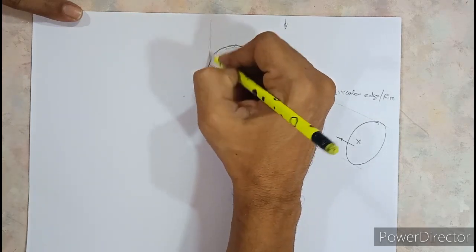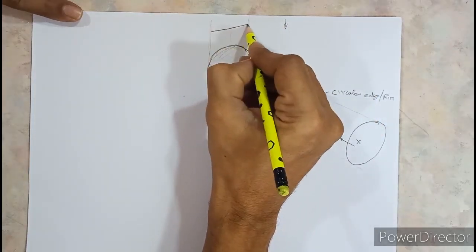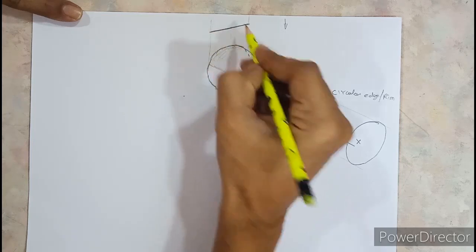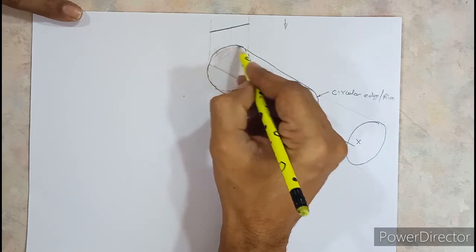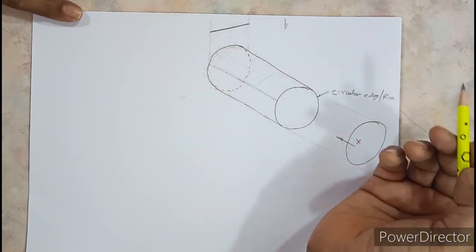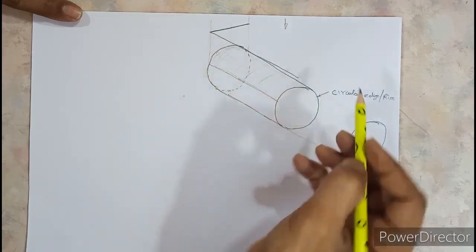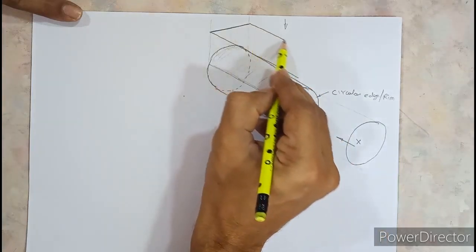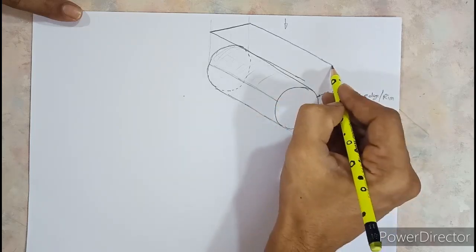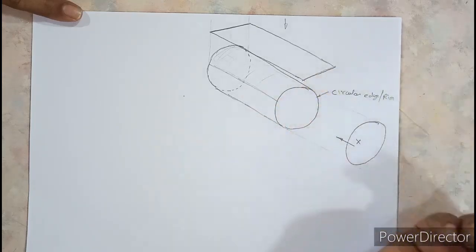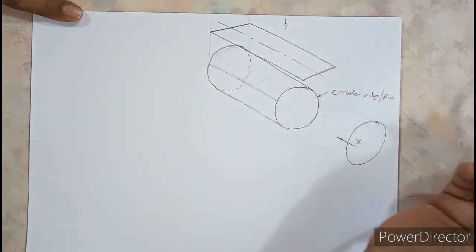So when you look in the top view, the rear circular edge will be seen as a straight line. So I'm drawing a line over here. Actually this line represents a curved edge. The edge is a curved part, but it seems to be straight. Similarly, this boundary of the cylinder will be seen as a straight line. There is one more boundary on the other side, which is one more straight line. And finally, the front circular edge will be seen as a closing line like this. That is how a circular surface is seen as a rectangle from the top view.